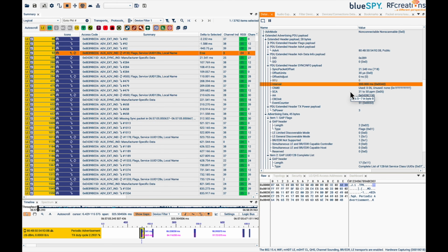And so what this means is that every packet will be known to the scanner, and based on an algorithm, it'll know exactly which channel will be used, rather than extended relying on the information being in the packets indicating which channel. From there on, it doesn't need to do that for the periodic advertising, and instead it can just know from the algorithm and plugging in some information what channel it will be on.